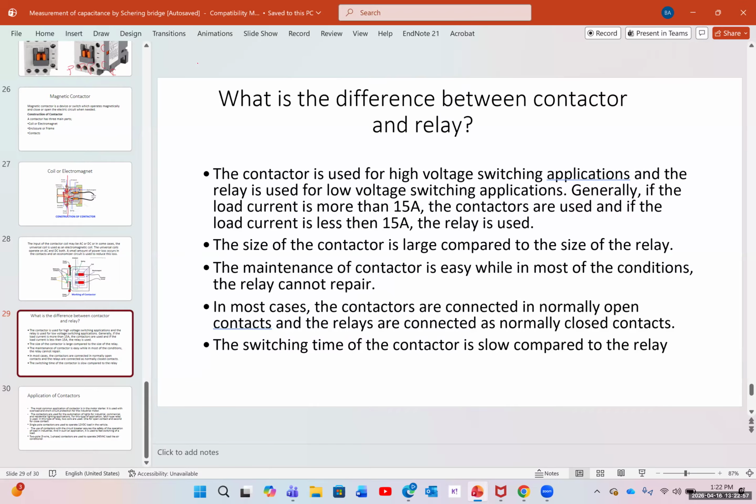A contactor works for high voltage, high currents, usually above 50 amps. Relays work for lower currents, below 15 amps. Contactors are slower and work at lower frequency compared to relays. Relays are for very high frequencies. Some of these relays also have the same mechanical structure as a contactor, so they are electromechanical. Some relays are purely electrical. They use transistors as switches, like MOSFET or FET or JFET transistors, something like that.